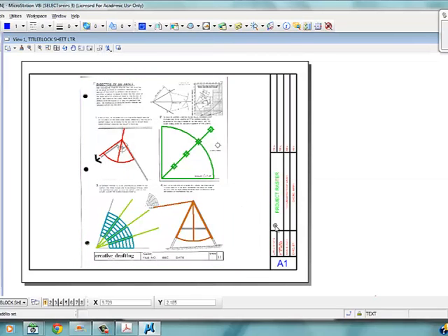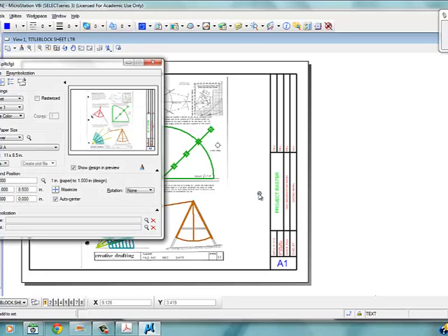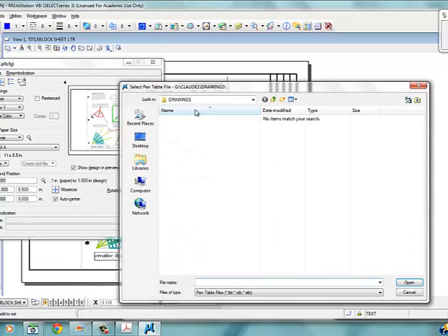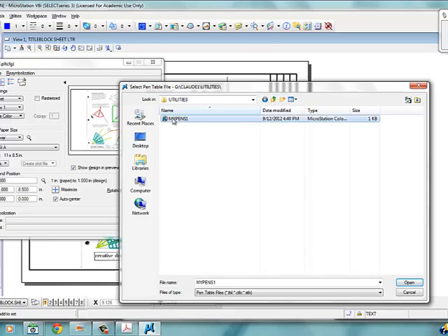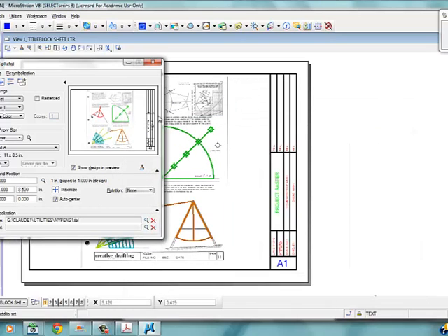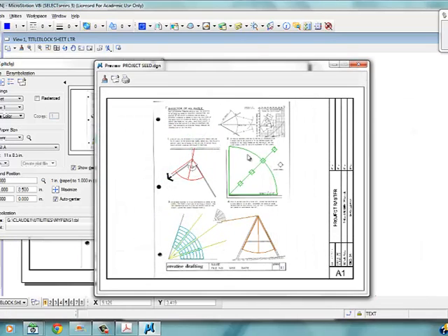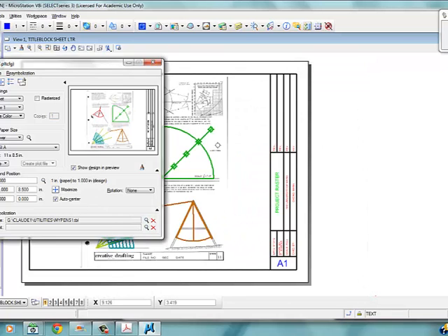So when we go to print this, now the one thing, our pen tables don't cover this, so it'll actually be a color drawing. We do a Control P. Resymbolization. We still want to attach our pen table, because that makes our title block. And if I do a fit view here, there's our drawing, our workbook sheet in our title block. So everything looks kind of cool. Close this out. We're just going to say print.